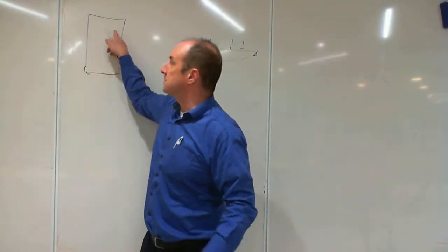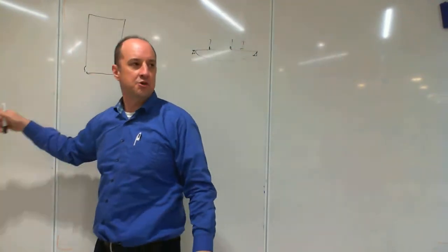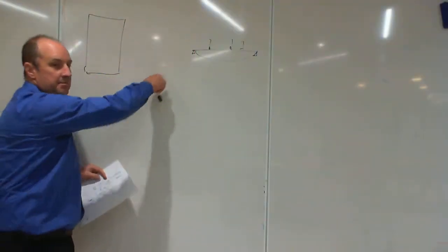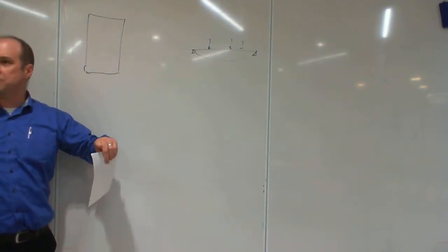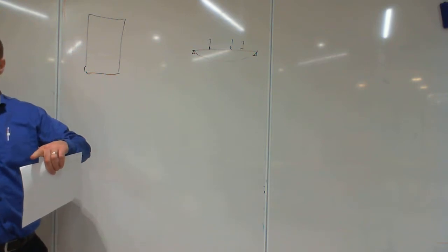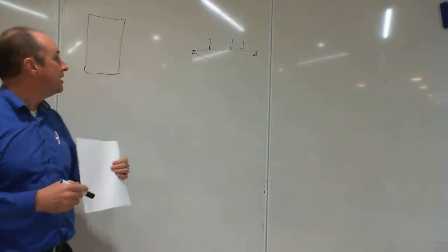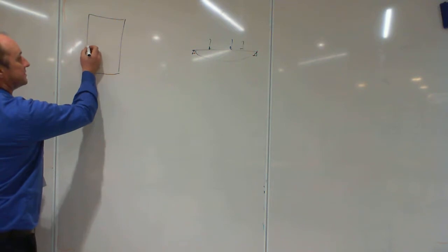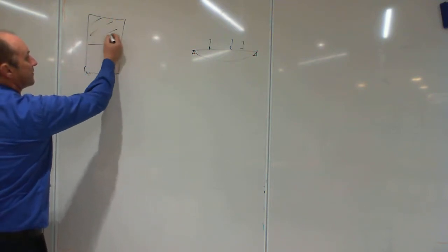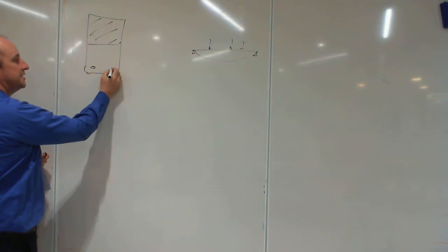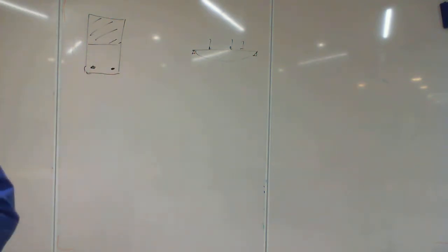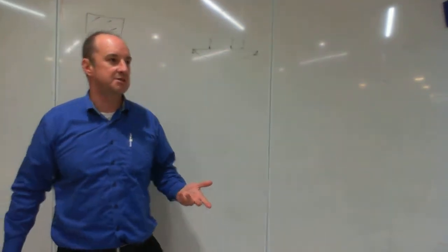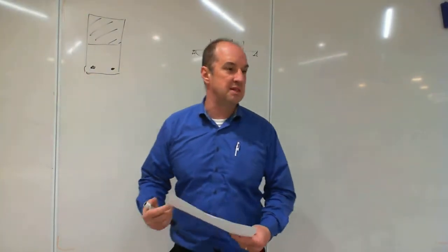We'll be assuming all our beams are rectangular, okay? We'll talk about T-beams and other things a bit later. So in a concrete beam in bending like that, you know that the top is in compression and the bottom is in tension, okay? If that's not clear, there's a topic on that fairly early on. And you know that concrete does pretty well in compression, so all that face goes into compression and the tension is held by the steel here, okay? Concrete has very little tension capacity, so it's there, but it doesn't really work for you.